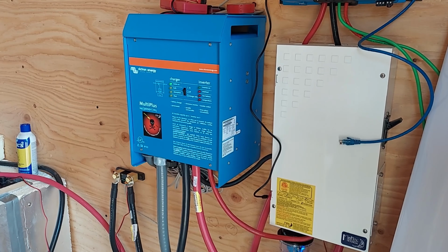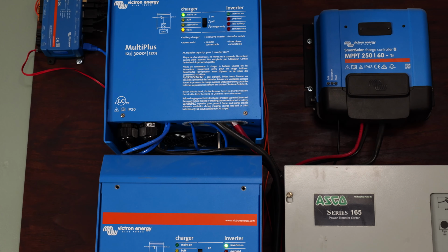The last behavior you may see in an inverter system is an instantaneous connect and disconnect, essentially a click-click. This behavior, at least in Victron inverter systems, is almost always representative of a bad neutral to earth connection or some kind of grounding problem in general.